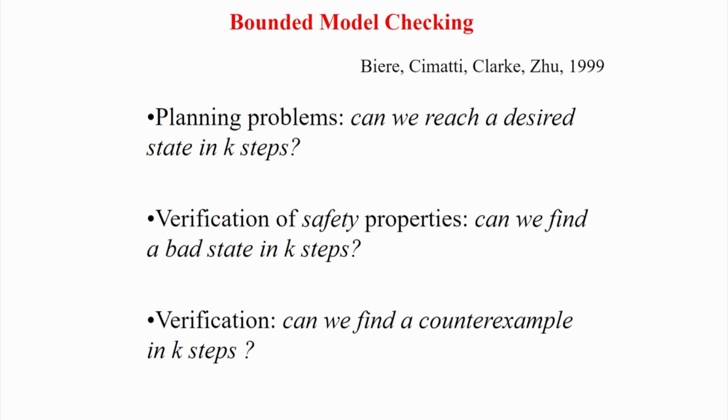But in symbolic model checking, we handled complexity by using binary decision diagrams, so that redundant variables are eliminated and we get a lot of compression. In bounded model checking, we think in a drastically different direction. Say, for example, we have to check a safety property that in all paths globally something should hold. A safety property can be like you have a microwave, the heating is on, and the door should be closed. That is a safety property which should be verified in all these states.